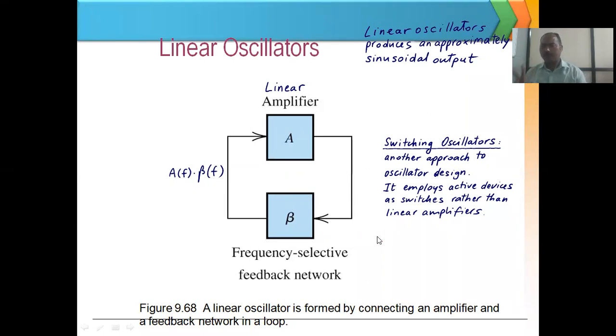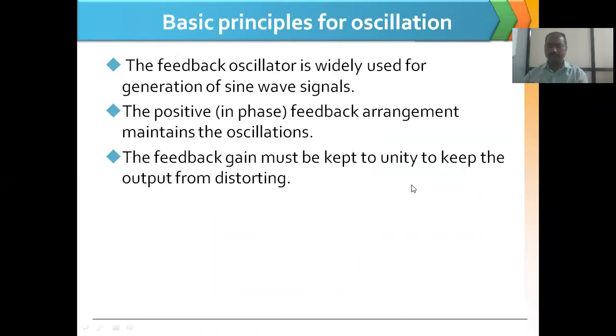For the generation of oscillation or RF signal, we need an oscillator, and for generating the oscillator signal we need two oscillatory conditions. The first condition is a phase shift of 360 degrees, which is also called 0 degrees. The second is that the feedback level should be greater than or equal to 1. Those are the two conditions for the generation of the oscillator signal. We will see the other things in the next session.